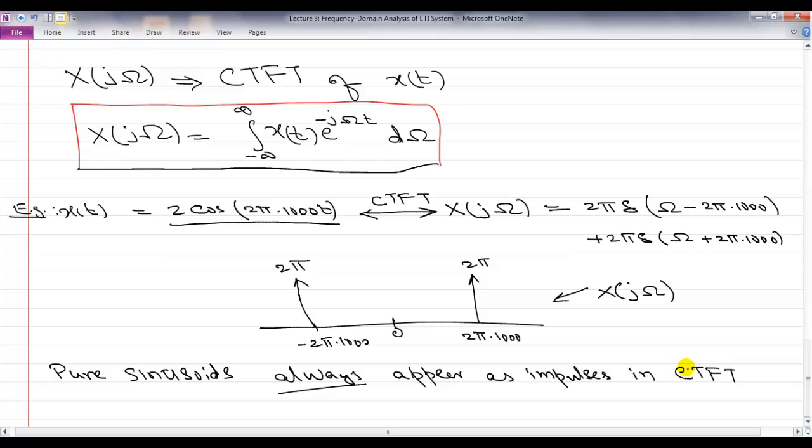So that's the meaning of what the continuous time Fourier transform does in terms of helping us understand the frequency content of an input signal. If you had a way to write my voice as a function of time, x of t, you could compute the continuous time Fourier transform of that x of t, and then you would know exactly which frequencies are emitted when I am talking.